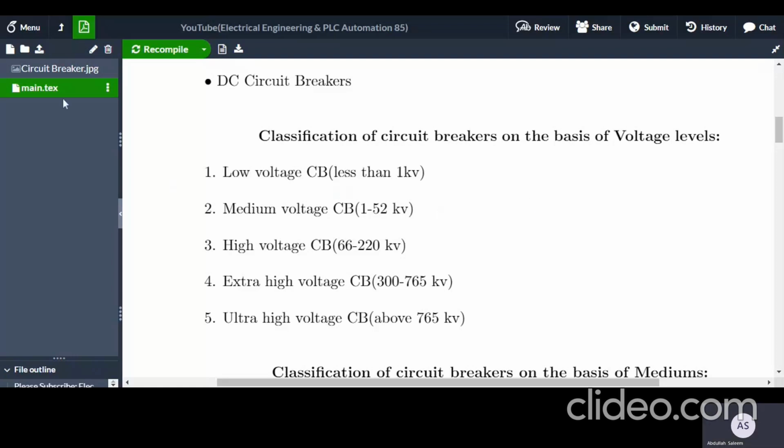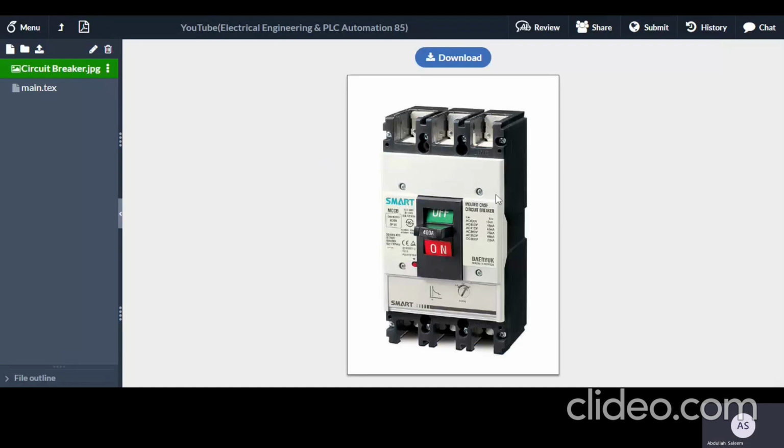So this one is the circuit breaker, and these terminals are known as incoming terminals. Here we connect three phases regarding phase sequence, red, yellow, blue, incoming to the circuit breaker, and these terminals are known as outgoing terminals, and from these the wires go radially outward and connect to electrical appliances. The operating current of this circuit breaker is about 400 amperes.